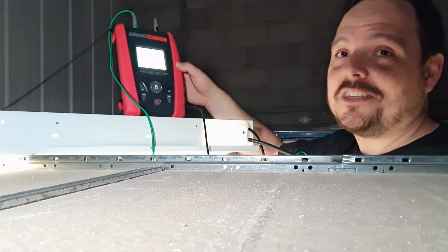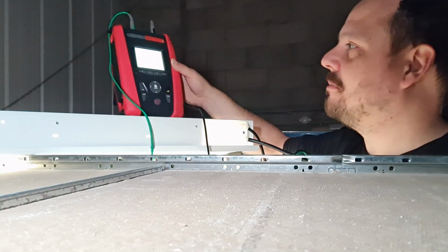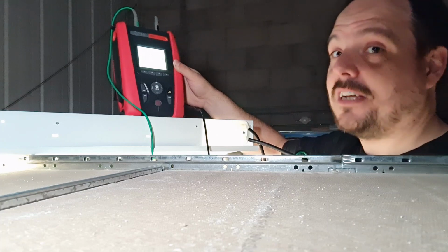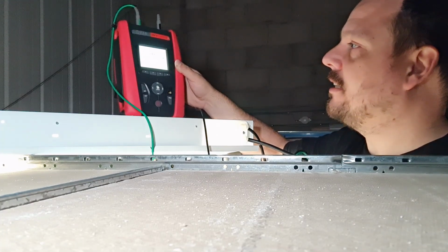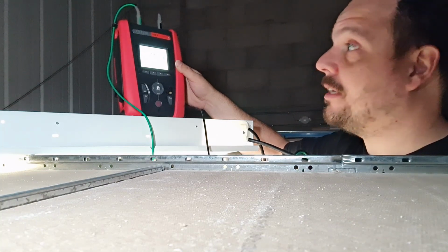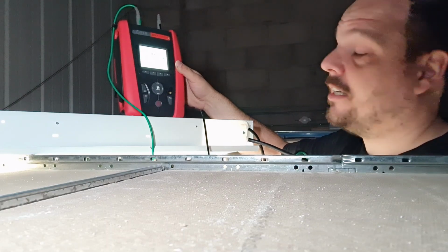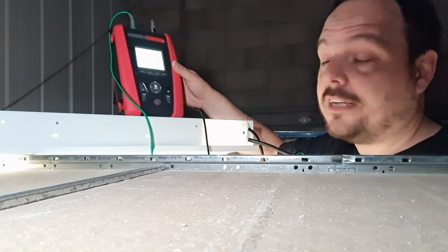It's making you aware as the tester that you might not have inputted all the required data into the instrument, and the value it's recorded isn't acceptable based on the circuit protective device it's expecting. So you can see in this case our ZS is 0.56 ohms. We'll see how that plays out with the calculations based on our ZE and our dead testing, and also what the PSC is at this end of line on the lighting circuit.